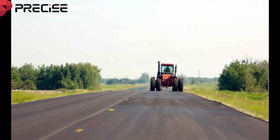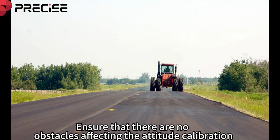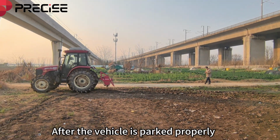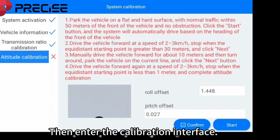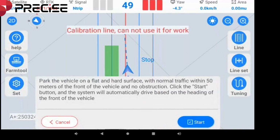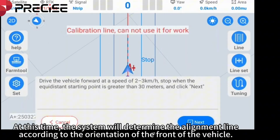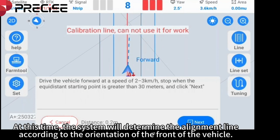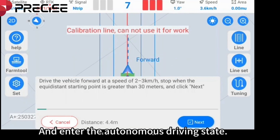Attitude calibration. It needs to be carried out on an open, flat and hard ground that is 10 meters wide and 30 meters long. Ensure that there are no obstacles affecting the attitude calibration. After the vehicle is parked properly, click Start. Then enter the calibration interface. Click Start. At this time, the system will determine the alignment line according to the orientation of the front of the vehicle and enter the autonomous driving site.